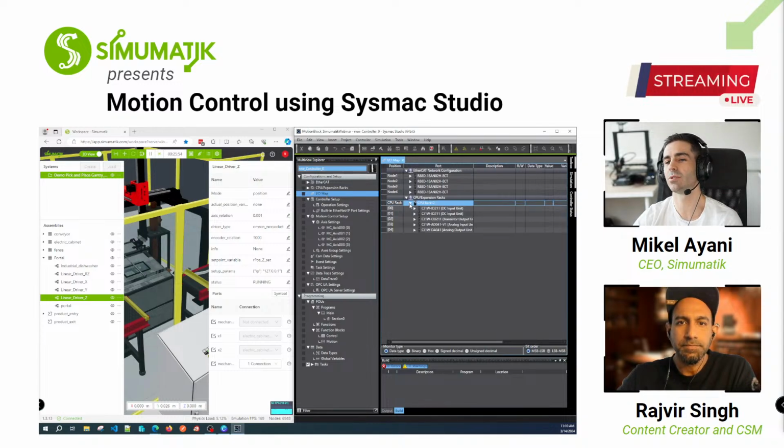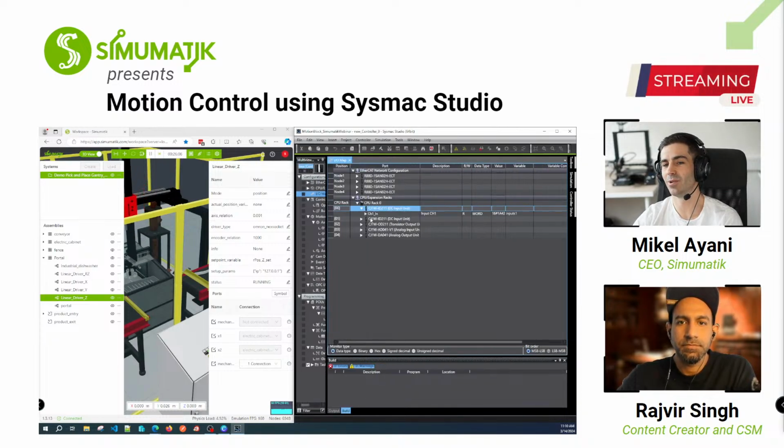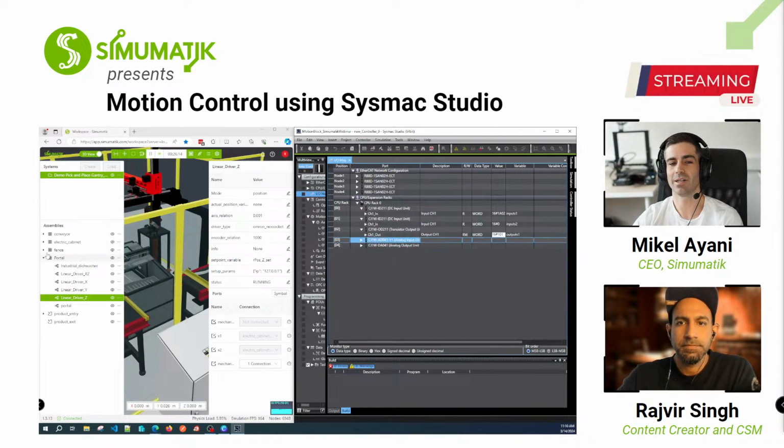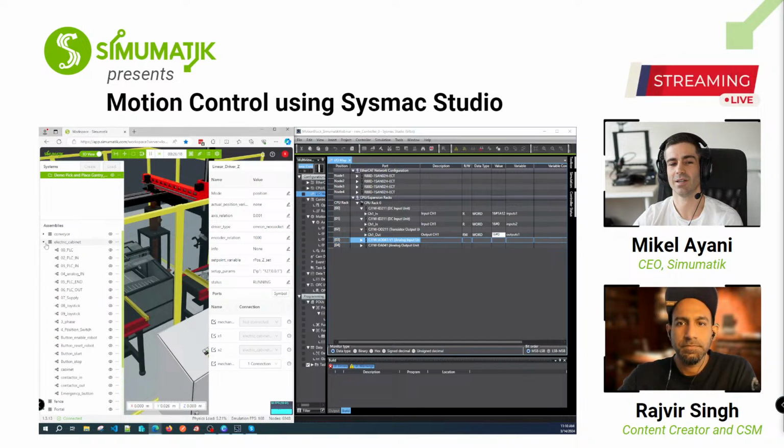For the inputs and outputs, it is super intuitive, because you just add the hardware here, input cards and output cards, and you set a name for each one. We see here input 1, input 2, output 1, output 2, and so on, and those are the variables we use in Simumatik for each card.